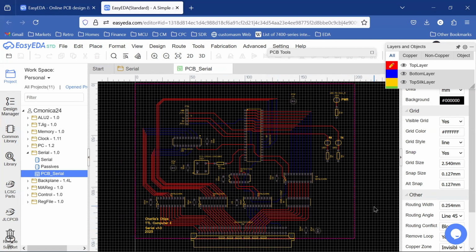Now, what I actually did here was, again, since our memory card is kind of our pattern for all of our expansion cards, I cloned the memory card project as a starting point. So that meant I didn't really have to do a lot of the component placement and the routings, right? So I got the card connector, I got all of this card connector routing and the routing here kind of for free. And then I deleted all the rest of the stuff and started my schematic work. So a lot of the routing was already done for me.